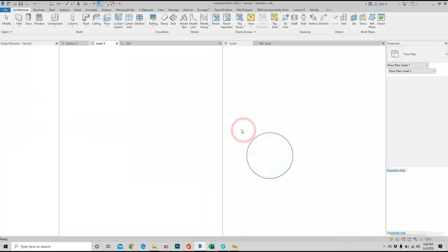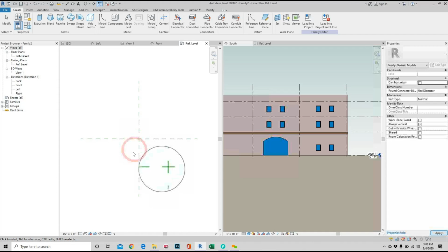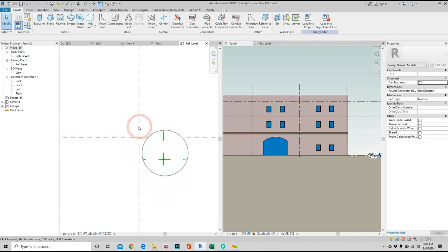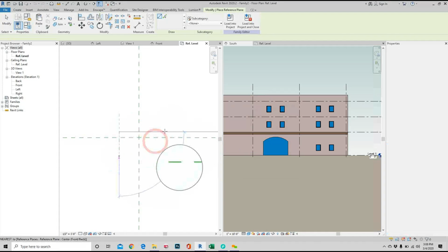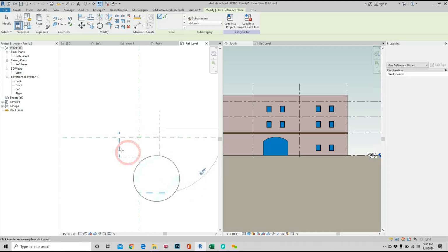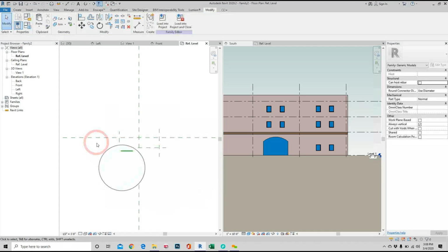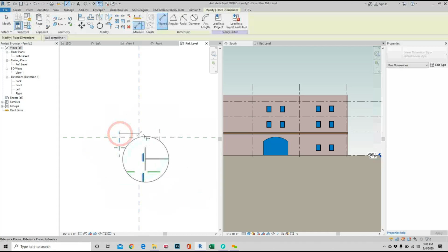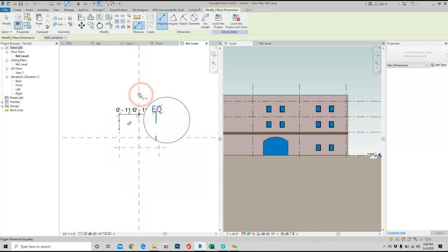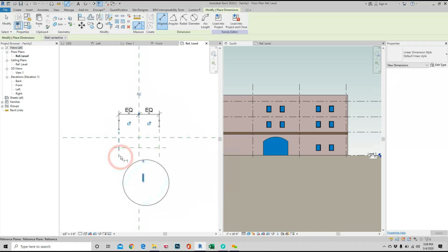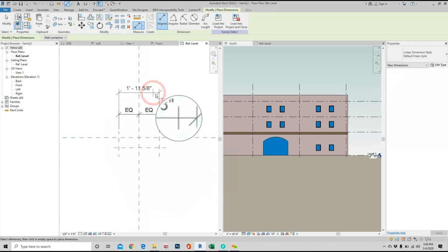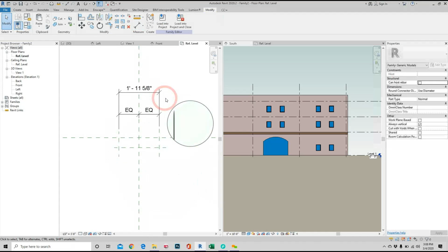And then, you open this family now. So let me go ahead, and this is, I imagine, the center. Okay, so the first thing we do, we create reference planes that would allow me to know exactly the dimension of this thing. So remember the sketch I drew? That's my pilaster. All right, I can go there now, dimension to the center of this, make it equal. So that way, and then I can go here to the back, and that would be my width.